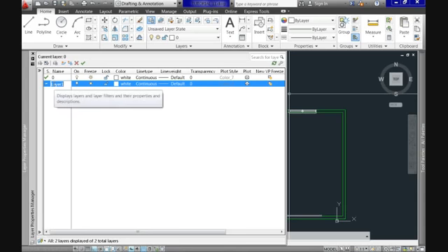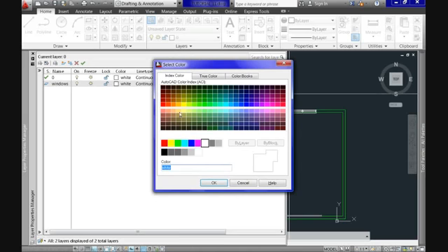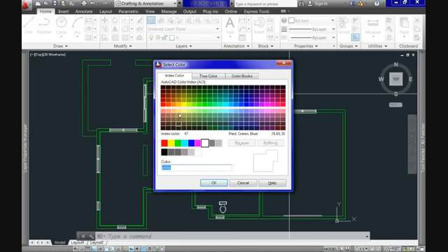It will create a layer with the default name Layer 1. As you see, it has the same properties as layer 0. Normally, you should use some type of standards for these properties, but the point is that we can modify all of these properties. First, let's rename it. If we click on top of the name in here, we can change it to the name we want. So let's name it Windows. Now let's modify the color. So we click on top of the small color square here, and this color window will pop up.